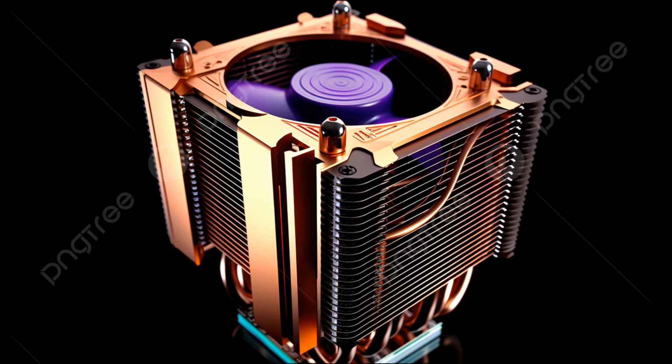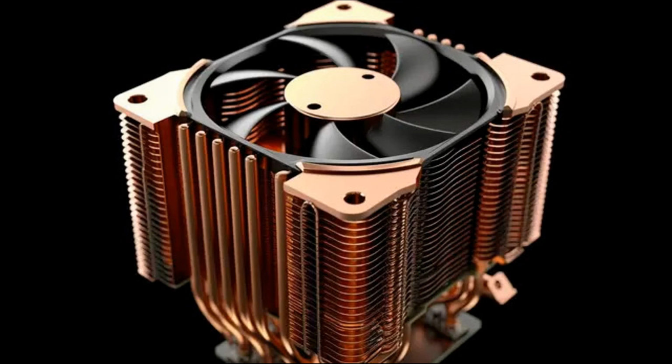Heat pipe heat sinks are commonly used in electronic devices and systems where high-performance cooling is essential, such as high-end CPUs, GPUs, LED lights, and power electronics. They are particularly effective in applications with limited airflow or space constraints, as they can efficiently transfer heat over longer distances and across different orientations. Additionally, heat pipe heat sinks are often integrated with other cooling technologies, such as finned heat sinks or liquid cooling systems, to further enhance cooling performance.